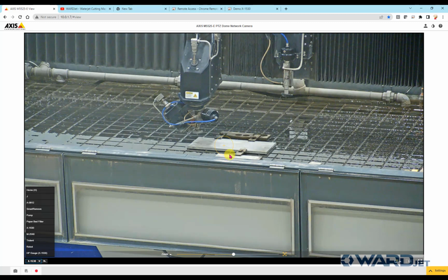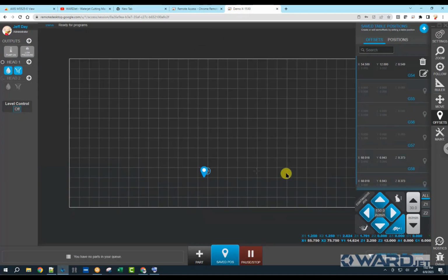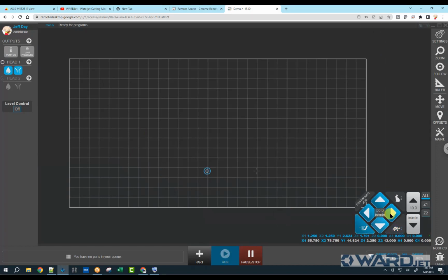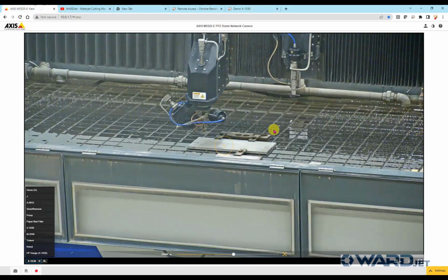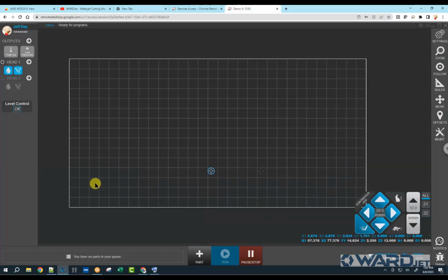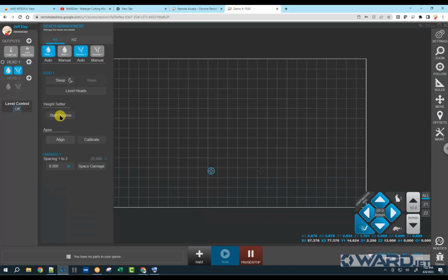Alright, so I'm just going to jog a little bit to the right to make sure that I'm over my material. So back to the controller. I'm just going to go into snail mode here a little bit and jog over a bit. Should be good there. We're going to run the height setter. So we're going to run it on head 1. Over here on the left, I can expand the head 1 menu. Click on Start Routine.